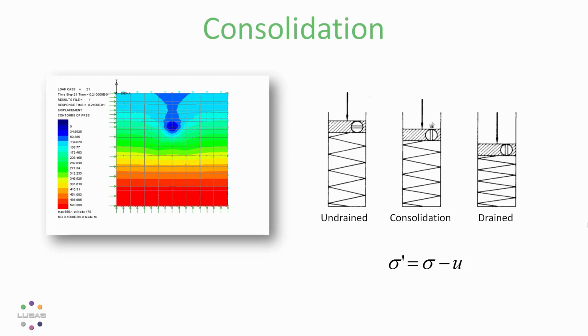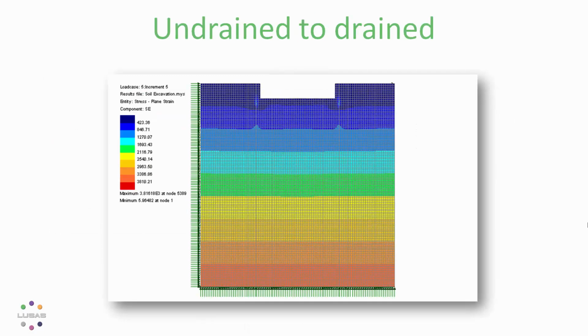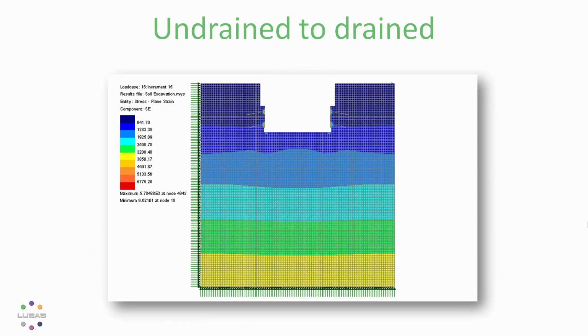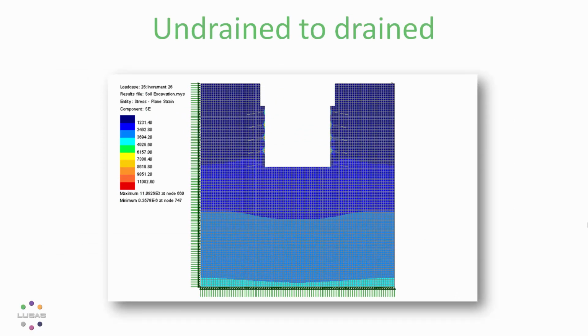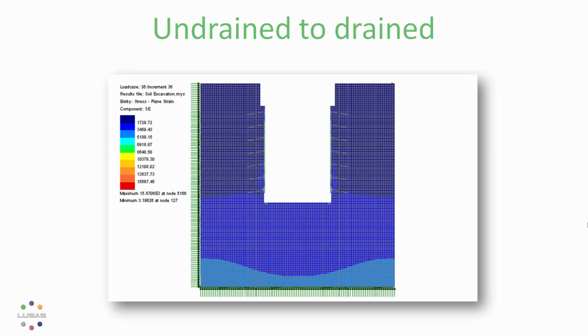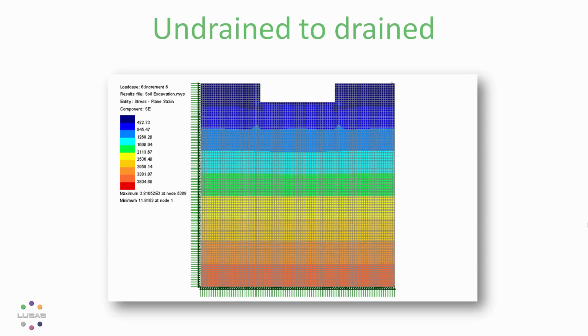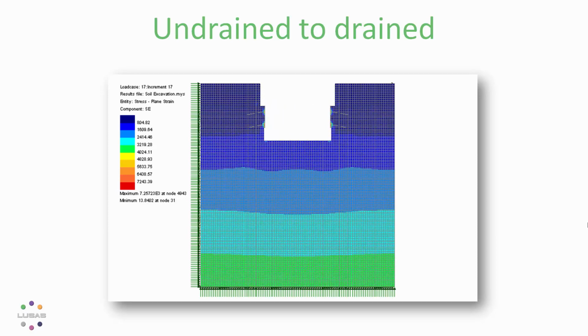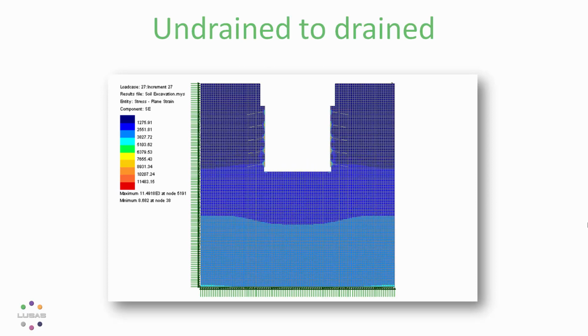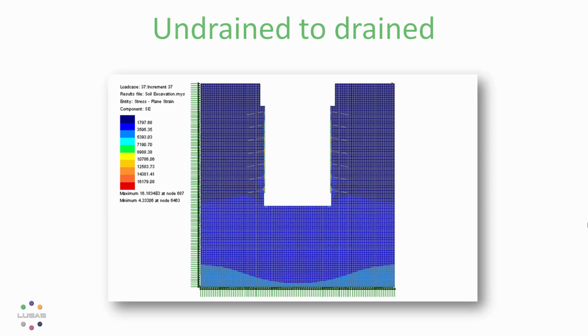However, now we have a shortcut from the undrained to the drained condition. This removes the need to explicitly model pore water pressure changes. With the assignment of one attribute, we can obtain the alternative response, with drained conditions typically being critical for cuttings, excavations or retaining walls where soil loads are being decremented.